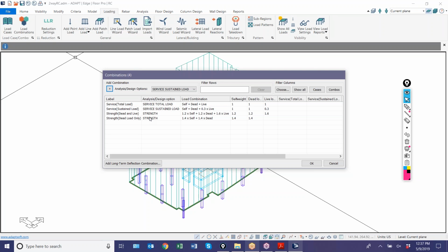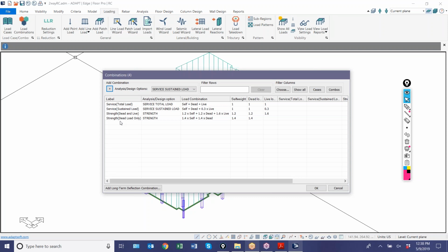The question was, well, if I have a model that has other types of loads, it might be lateral, it might be other classifications, I may need to have several more load combos. So how do we get those into the model? And the short answer is you have to build them in the model. Once they're built one time, you can use the IMP exchange to actually import load combinations between models. We have this internal tool, again, that has not been released that would actually calculate, or let's say populate, all of the load combinations into a model.